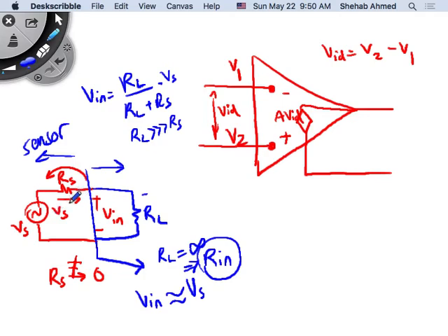This sensor will produce a voltage corresponding to the physical phenomena, but connecting it to the circuit will make some current flow. If you flow some current through any material, this will cause some voltage drop. Since it's a conducting material, it will have some conductivity. R equals rho L over A. So anything with a conductivity will have a resistance, right? So Rs exists. Rs is just the internal resistance, the Thevenin equivalent resistance of the sensor.